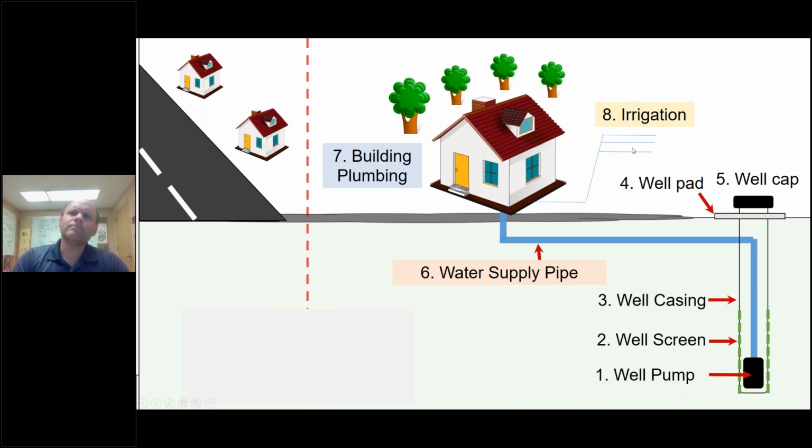So for the very small water systems, you may have a single well with multiple homes on that well, and you may or may not have a storage tank. Here for well systems, you can have concerns about the fire burning over the wellhead. It may or may not be inside a well house. If it burns in the well house and the well house falls into this open well, because some of these are shallow wells, you can have contamination. You can also have these casings. They may be metal casings, they may be PVC or other plastic casings, and they can burn and melt down below ground surface.